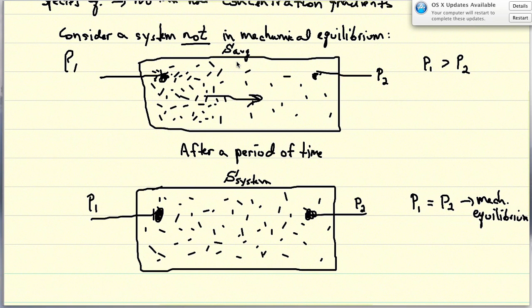So after this period of time, from a second law perspective, this entropy generation is greater than 0. So what does that mean? The entropy of the system here is relative to this average entropy that we started out with when we had the non-equilibrium. Entropy generation can only ever be positive. So the entropy of the system after the process is greater than the average entropy, right?